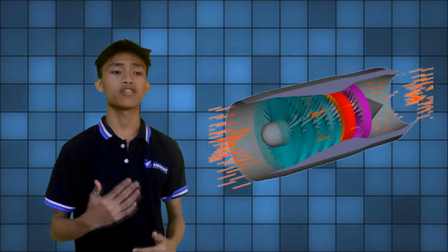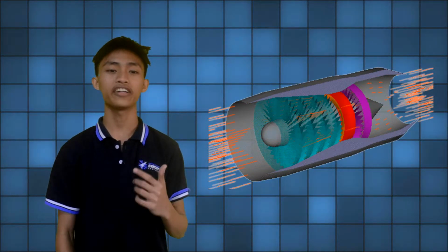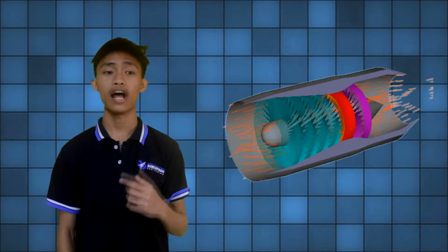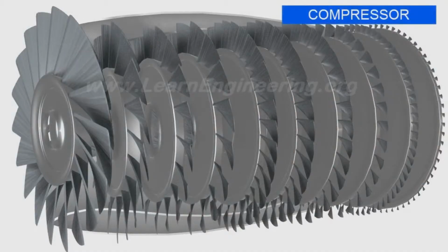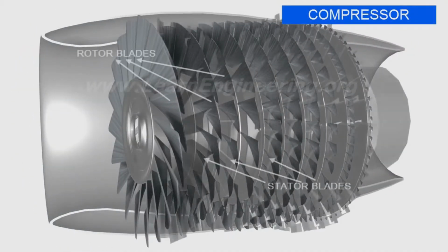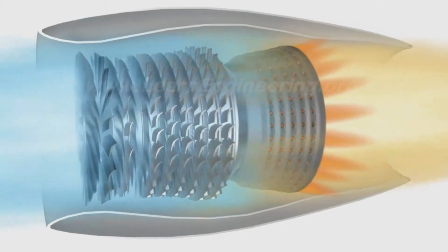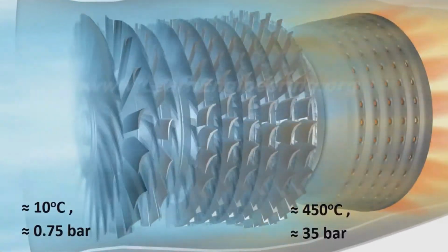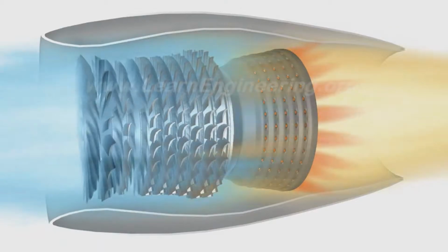The turbojet is an air-breathing jet engine usually used in aircraft. It consists of a gas turbine with a propelling nozzle. The gas turbine has an air inlet, a compressor, a combustion chamber, and a turbine. The compressed air from the compressor is heated by the fuel in the combustion chamber, and then allowed to expand through the turbine. The turbine exhaust is then expanded in the propelling nozzle, where it is accelerated to high speed to provide thrust.